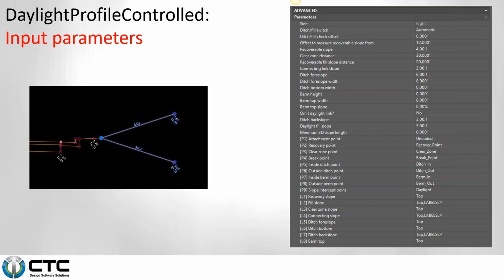This is the benefit of a custom subassembly with all 3 of these, is that I have the ability to come through and customize these codes. These codes, when linked with the proper code set style, will allow our corridor to build properly and to visually be what we want it to be displayed. So having these customized codes in here just makes things look the way that we need them to look.